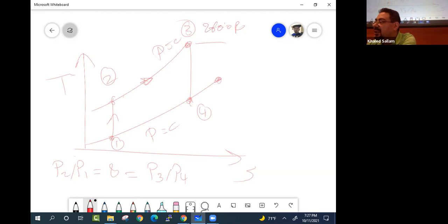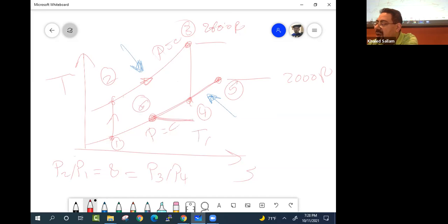So he will heat it in supplementary firing a little bit to go to 5. And so 5 is heated all the way to 2000. And then you add fuel in 2 parts. You add fuel here, and you add fuel here. And then you expand, so that you can generate steam all the way down to 6. And you say T6 is 800.